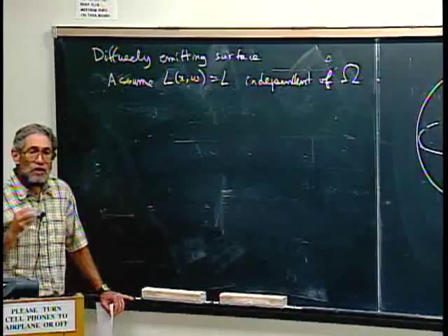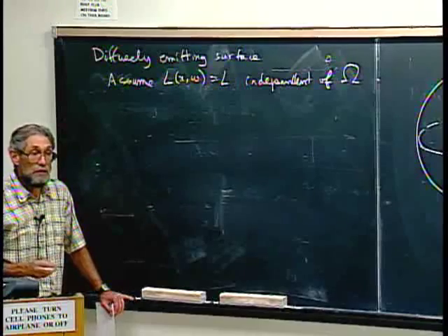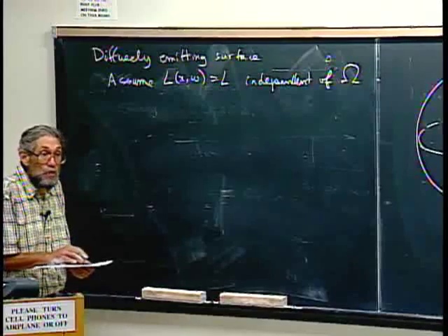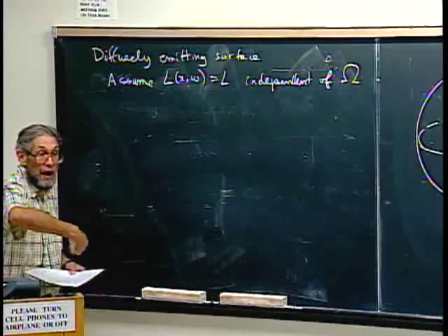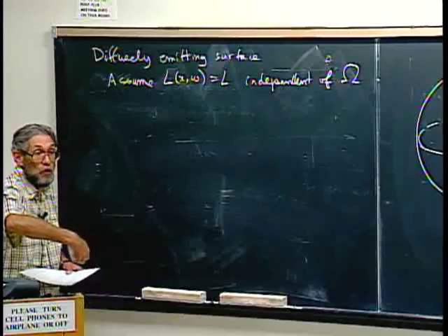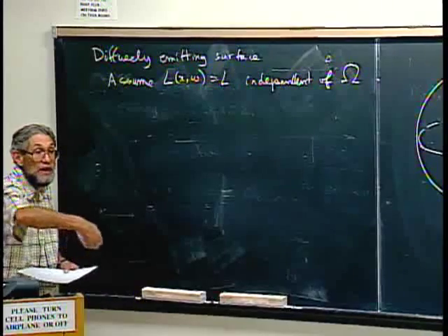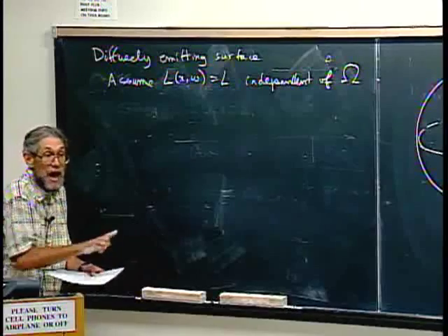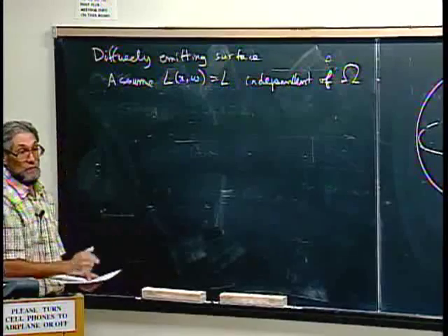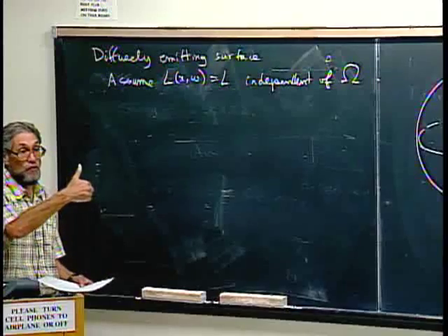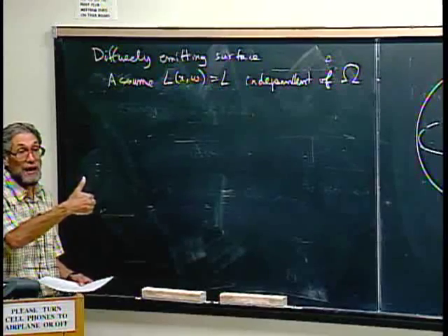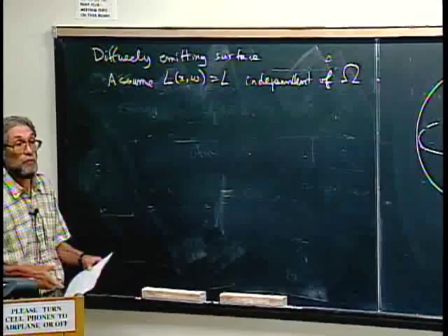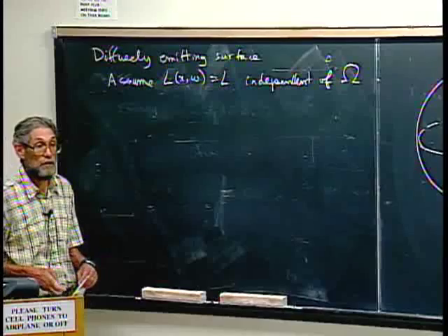So if the light looks equally bright in all directions, from what I just finished saying, it's not actually an equal amount per unit surface area flowing out in all directions. Because of that foreshortening factor, if it looks equally bright, it's still actually less per unit area leaving in diagonal directions than straight up, normal to the surface. But because of the foreshortening effect, it appears equally bright in all directions. That's what a diffuse emitter looks like, a very rough surface.